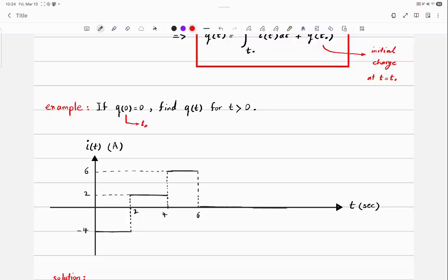Someone else do part C for me, please. Yep. It's going to be 10 volts because 10 volts across element B and its sister in parallel will be the same voltage across both. Do you agree with him? That's a very important point in your learning for this course. He just mentioned that B and A have the same current. Do you agree that B and A are in series? So series elements have the same current.